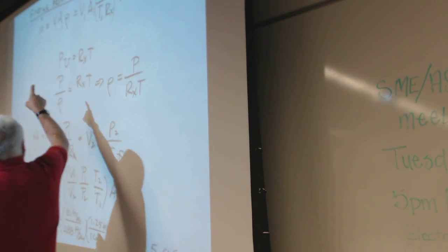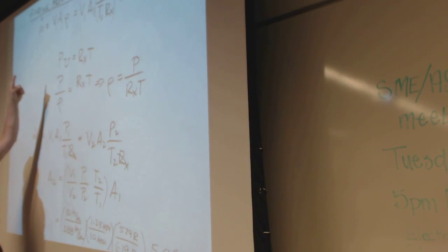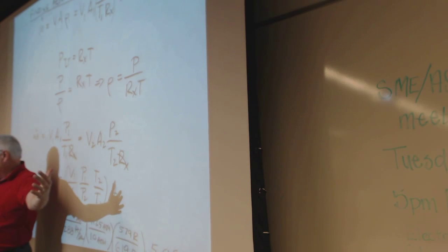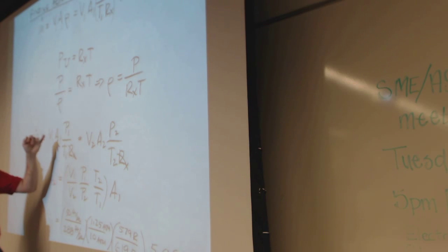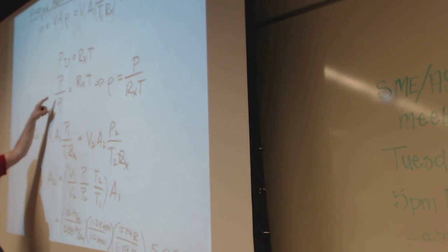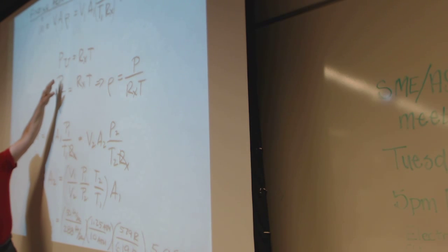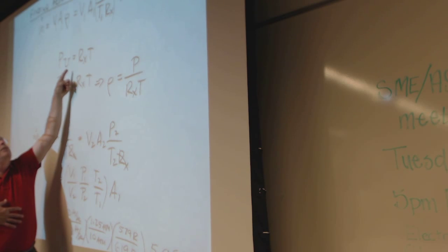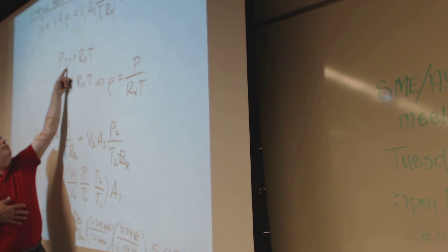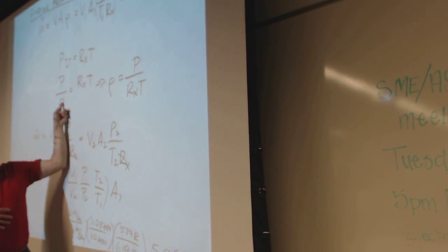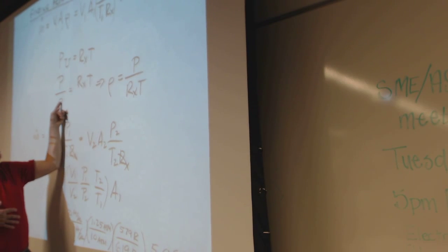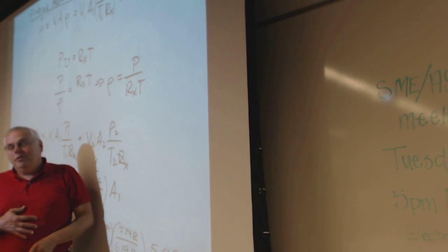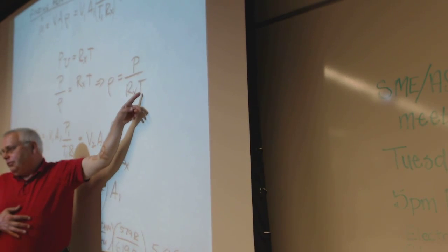Volume flow rate is the velocity times an area. How fast is it expanding? That'll get you a volume flow rate times density. In our version of the ideal gas law, it's P times specific volume, Pv equals RT. This is the inverse of density. So if you solve for density, density is absolute pressure divided by R times T, absolute temperature, ideal gas law.